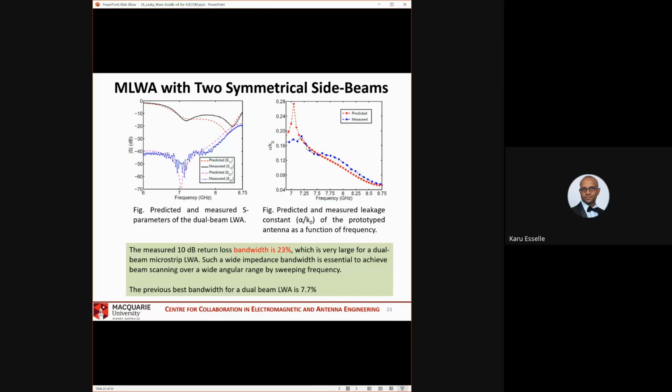In general, alpha decreases with frequency. So higher frequencies decay slower, right? Less alpha means slower decay. They decay slower, and that's why at higher frequencies you have an increase in S21.